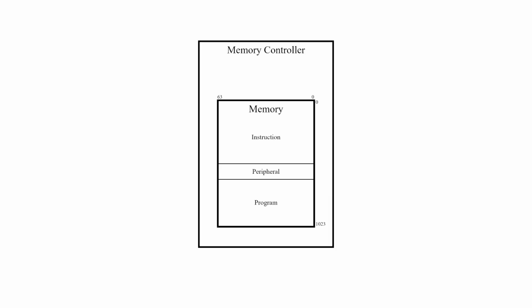Wrapped around this module is a memory controller block. This piece of logic interacts with all the other blocks, orchestrating their memory access in a round-robin fashion. Technically, there is a request grant access interface, but I kept things simple for now.